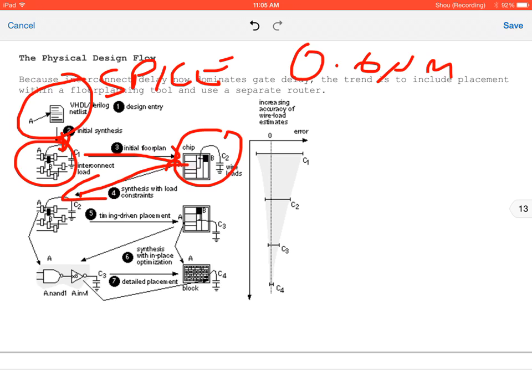So basically we're going to counter something called T junctions. These are very common, where you have a short stub T and then the long part. You want to synthesize this first so you can bring them as close together and then deal with the other portion. Because if you deal with the long part and mess with that, then you incur area overhead.